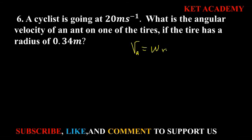In this case, it means that our velocity will be in meters per second because rad is unitless. So in this case, we're looking for omega, since we're looking for the angular velocity. So omega will be equal to velocity divided by the radius. Our velocity there should be 20, divided by the radius, which is 0.34. So doing our calculation, we are going to have 20 divided by 0.34.